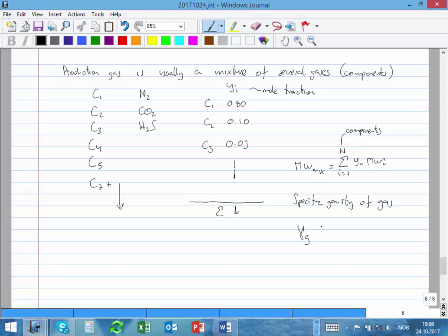But usually in SPE, the Society of Petroleum Engineers, we try to always use only a capital letter for a variable, and then the rest I can use as many subscripts as I want, but I have to have only one capital letter. So I prefer to use gamma gas, and that will be the molecular weight of the mixture divided by the molecular weight of air. Okay, and the air is 28.97. Yes, you have to check if that's correct.